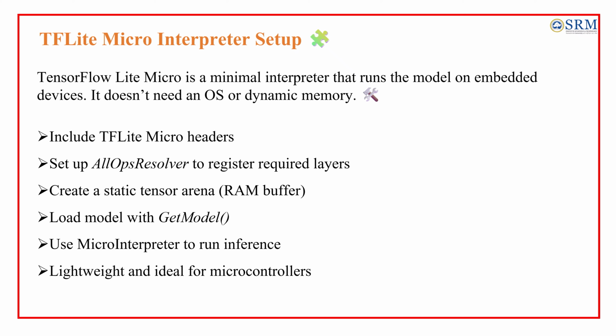The setup includes the TFLite Micro headers and an all-ops resolver to register the required layers, creates a static arena, a RAM buffer, and includes the model with get model. Use a micro interpreter to run inference. So this environment ensures our sine wave model can actually run on hardware.